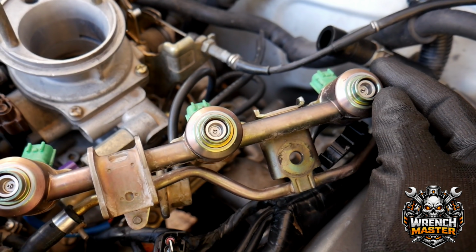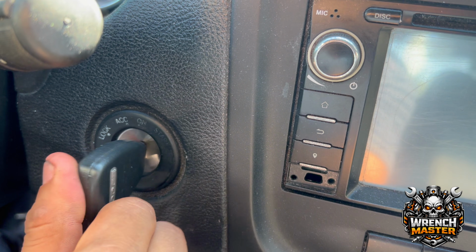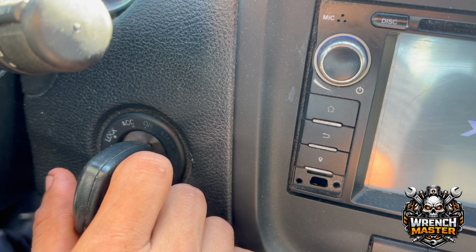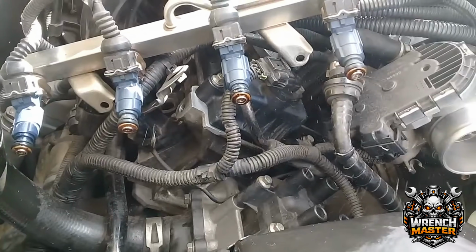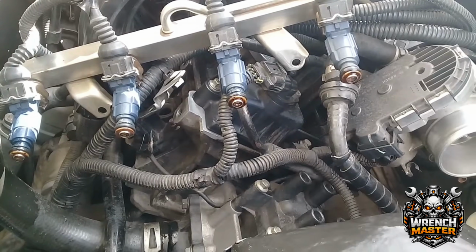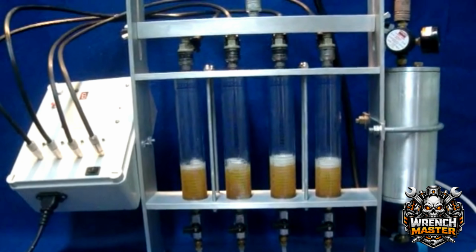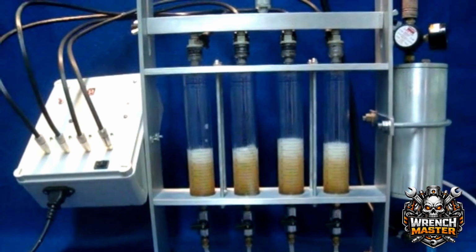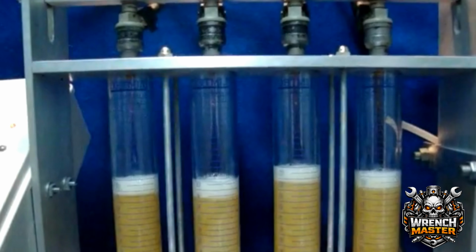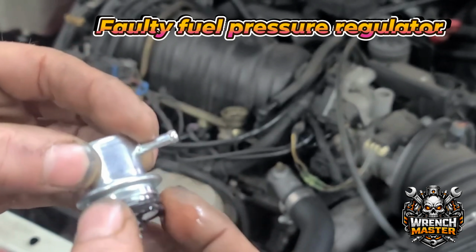To diagnose this condition, remove the injector rail while keeping the injectors connected electrically. Turn the ignition key to the on position several times without starting the engine. If you observe any injector leaking or dripping fuel, that injector is faulty and must be replaced or cleaned ultrasonically. For a more accurate diagnosis, send the injectors to a laboratory flow test bench to verify their fuel flow rate. If one injector delivers more fuel than the others, that injector is defective and must be cleaned ultrasonically or replaced.